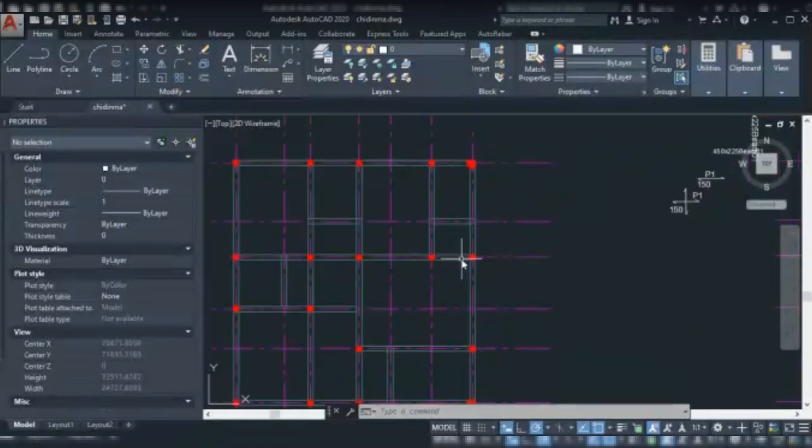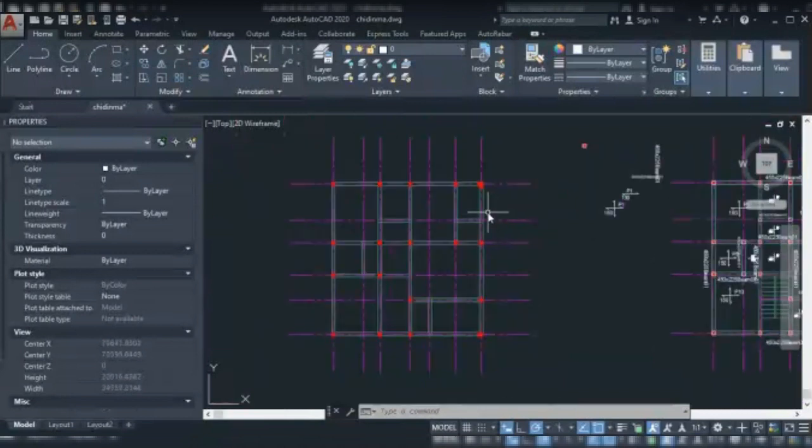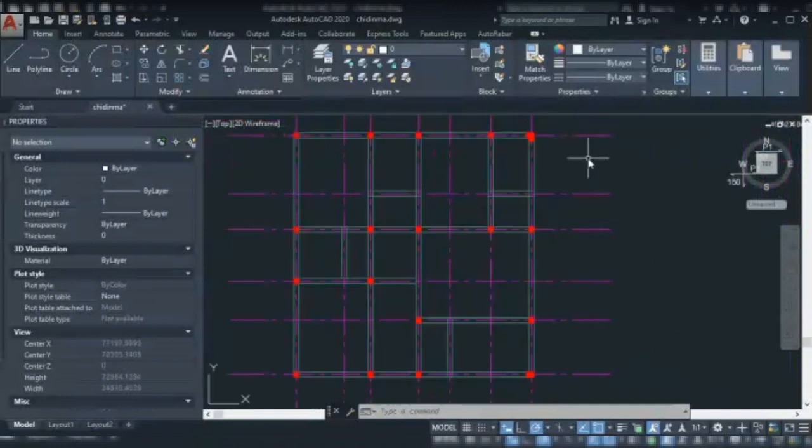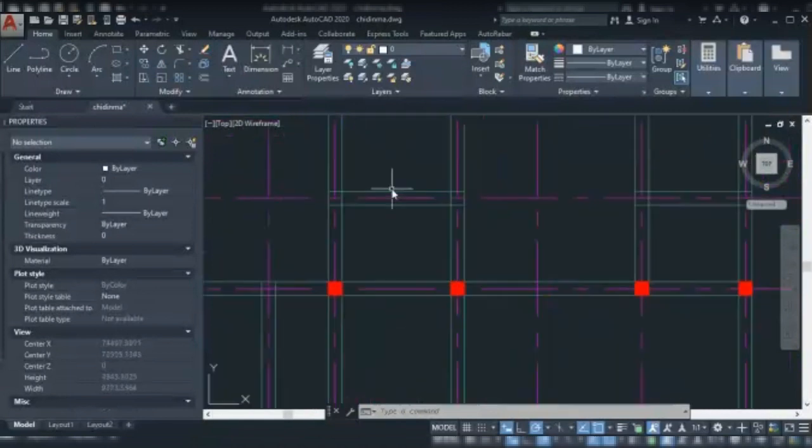What we have is a pitch roof. That is your hip roof, or this normal common roof you see around. So the dead load and the live load, the total should be 2.5 kilonewton per meter, uniformly distributed, 2.5 if I'm correct.